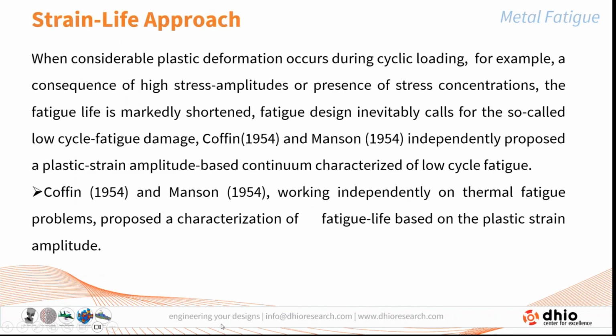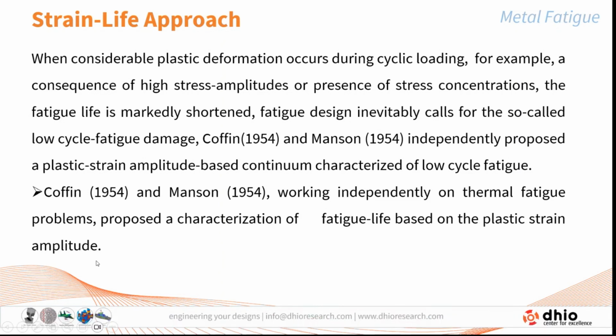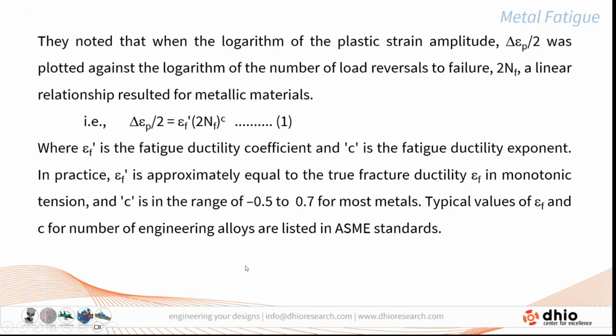Then we have the strain life method, and this is widely used for low cycle fatigue, where high stresses are induced. Coffin and Manson were the first people who arrived at the effect of high stresses caused due to thermal fatigue, and they developed the plastic stress-strain relation.